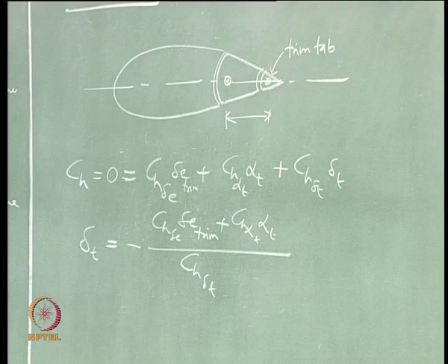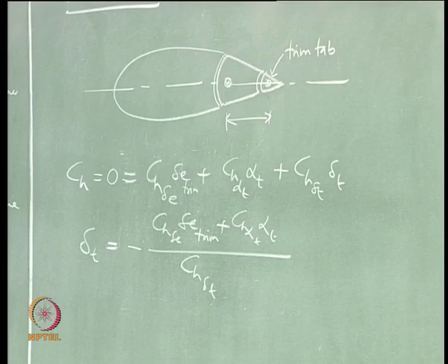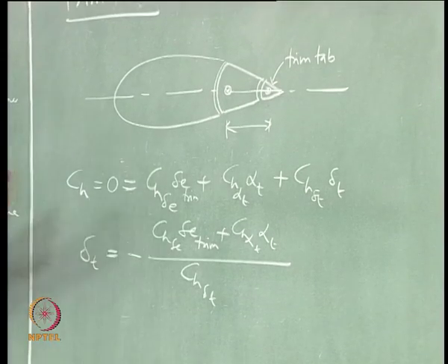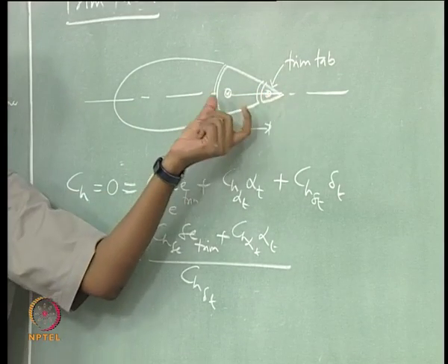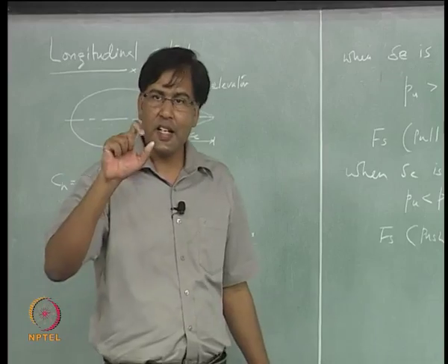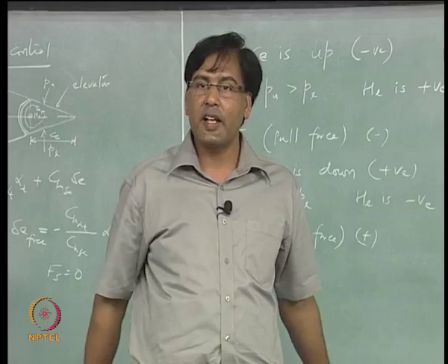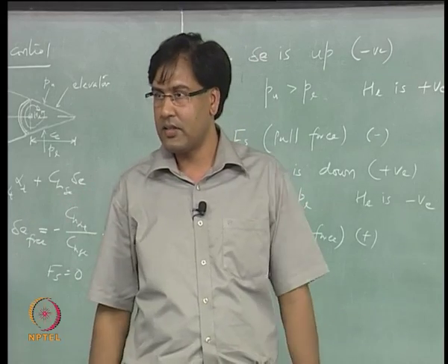So what will the pilot do actually here? Now he only has to play with this tab and not with this whole elevator, right. So once he sets the trim tab, he is actually setting the elevator angle.